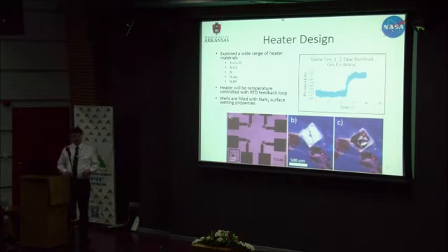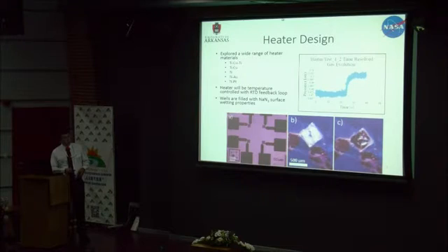One cool feature of this is we fill the wells using a surface wetting technique. So you can't see it, but there's a well here over each heater. The wells are created by optically transparent material. This material is a polymer, SU8 polymer, and it's hydrophobic. The heaters, though, are hydrophilic because they're a metal conductor. So how we fill them up is we take sodium azide, dissolve it in water, dip coat the chip, shake off the excess solution, and the solution will preferentially stay in the wells and run off the rest of the device. Then you just let the water evaporate, and you have a populated well. You can do this for tens or ones or thousands at a time.